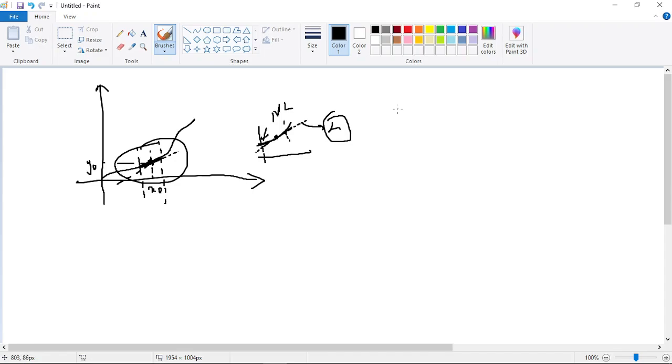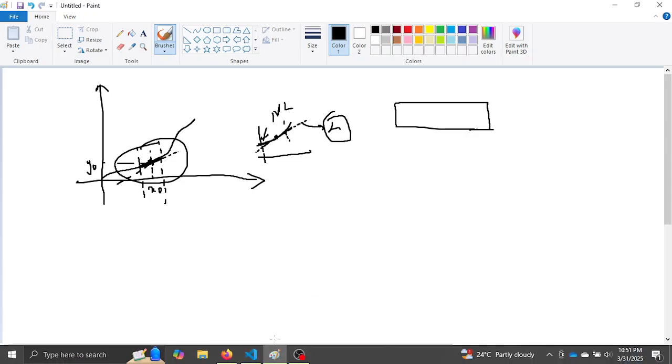But in the context of the synchronous machine, we have a set of differential equations that has to be linearized, and there may be algebraic equations that come from the load flows, and the dynamical equations that come from the equivalent circuit or equivalent model of the synchronous machine. So in such a context, how will we develop the linear model?